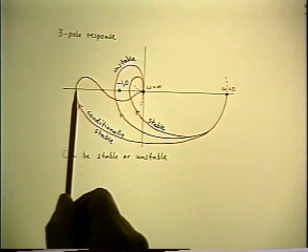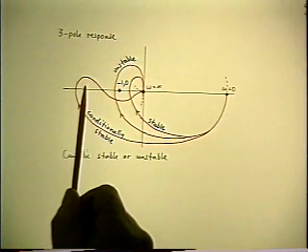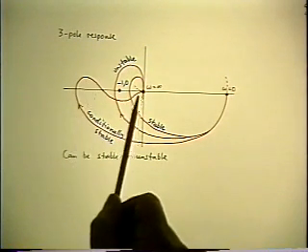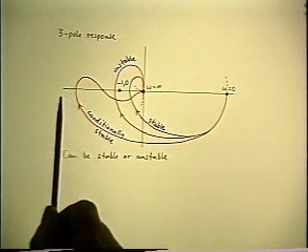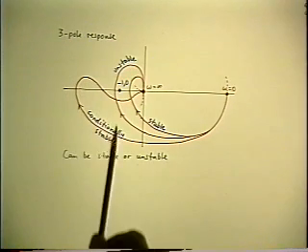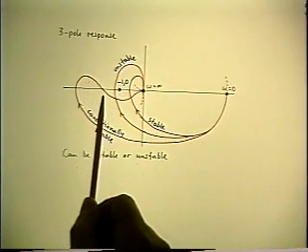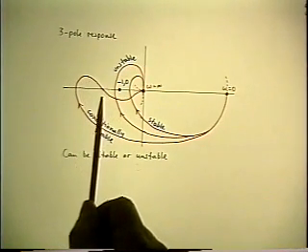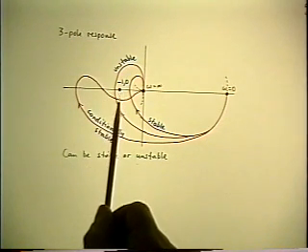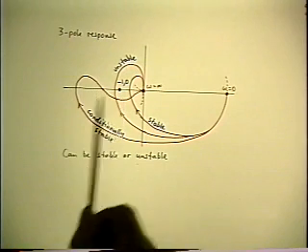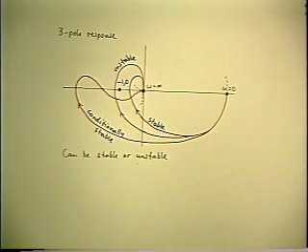the phase angle has actually increased beyond 180 degrees, while the magnitude is bigger than 1. But what saves it and makes it stable is that the phase comes back below 180, and when the magnitude is going through 1, the phase angle is below 180, which is what makes the contour avoid the -1 point. So that's known as a conditionally stable system.